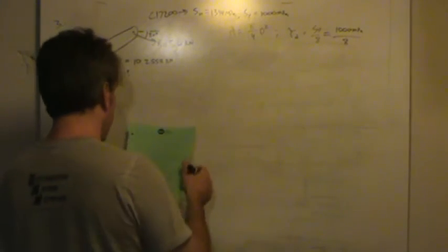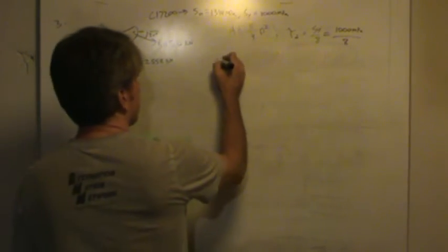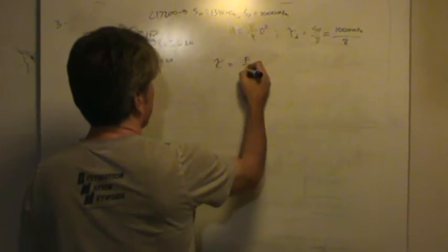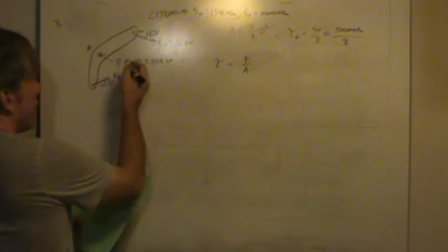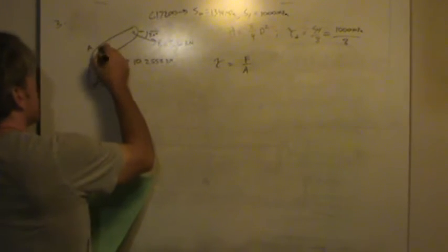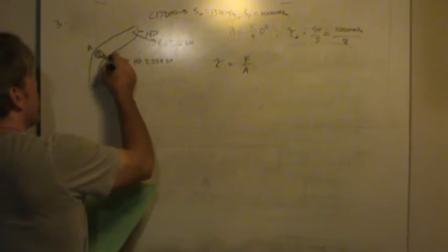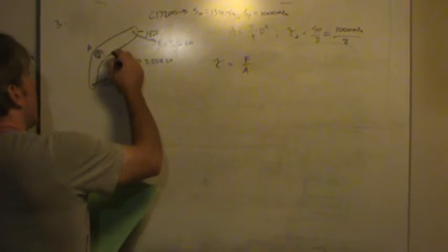All right, so that's what I'm going to use, and basically the shear stress would be equal to the force divided by the area. So the area we're talking about, let me expand this just a little bit, the area we're talking about is whatever area we end up with from designing the diameter of this pin.